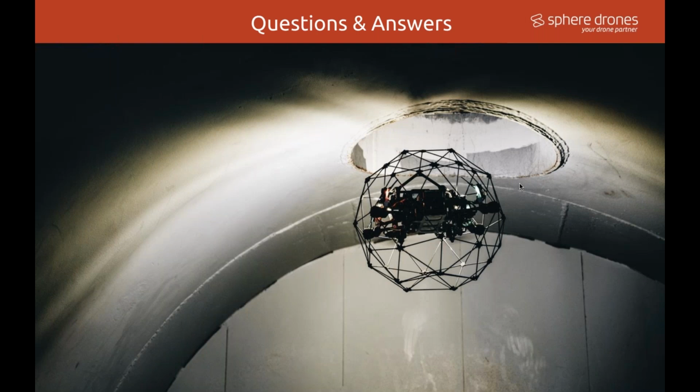There's a few questions around photogrammetry, whether you're utilizing the photos or the video. Just to clarify, you are pulling frames from the video. Yeah, at least in Pix4D, we have the camera model in the database, because you need a camera calibration model to map the intrinsic distortion of the lens and the camera. And we have that for 4K video, full HD video, and also the 12 megapixel stills that you can take during the flight.